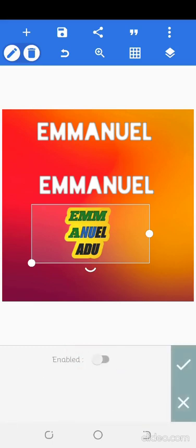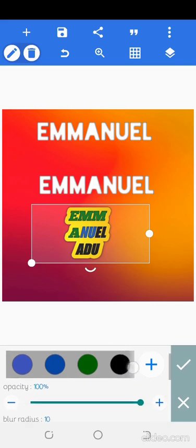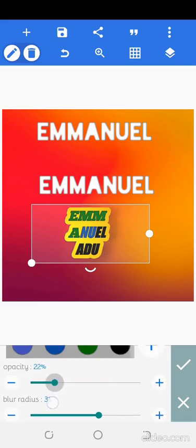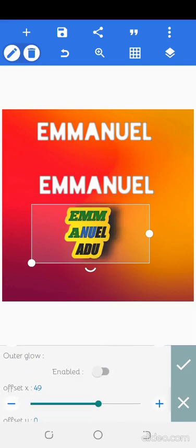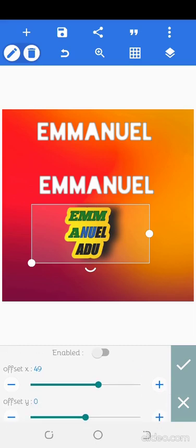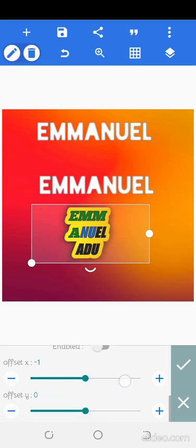Now shade also gives a shade to the text. Now opacity talks of how exposed the shade is. You can treat the radius. The radius makes it sharper or more blurred. Good. Now these ones are offset. So where should it be shifted to? You can offset it towards the x axis, meaning horizontally, then the y axis, meaning vertically.